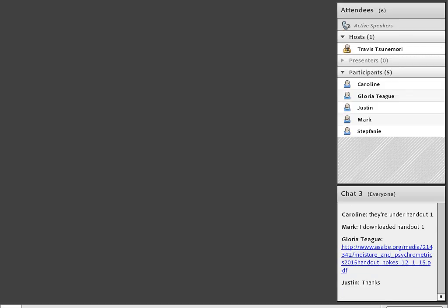Okay, so if we know the amount of water in a bushel, which is 8.1 pounds, then we could subtract that from 60 pounds and find out how much dry matter we have. So in a standard bushel of soybeans, there's 51.9 pounds of dry matter. And this is important because now we can use that information to find out how much water we need to remove when the soybeans are at 25% moisture content.